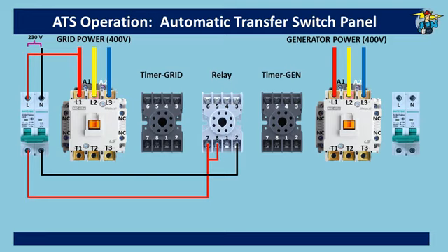Now, relay output from number 6 is connected to the grid timer power supply at number 7. Neutral supply is also connected to number 2 of the grid timer. This will make sure, as soon as the relay is powered, normally open points of 8 and 6 will close, and grid timer 2 gets power simultaneously.